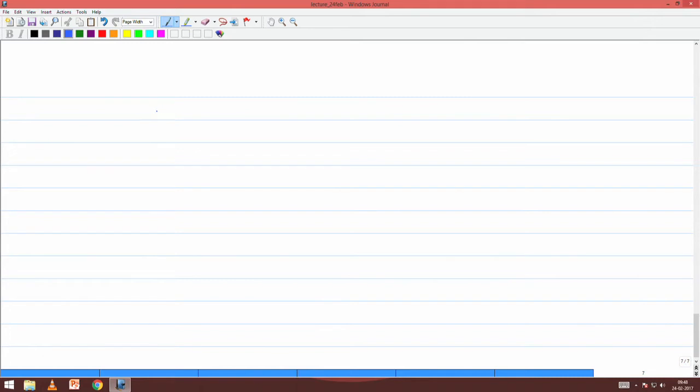So, the acoustic intensity working formula is simply half of the real part of pressure times u x star, right. It is u x if you are interested to calculate the power flowing through an area which is normal to the x direction.